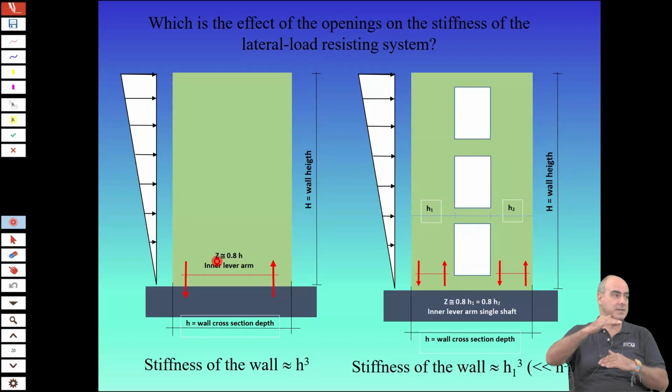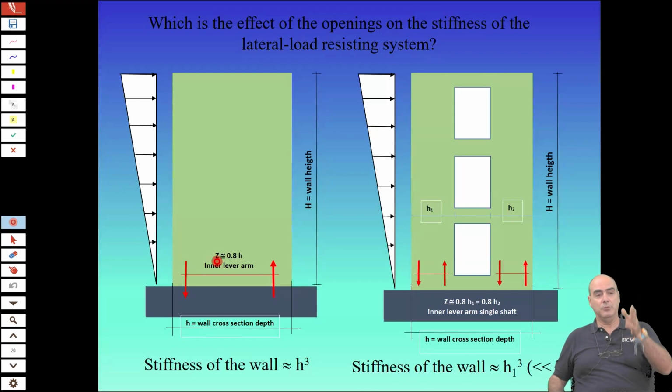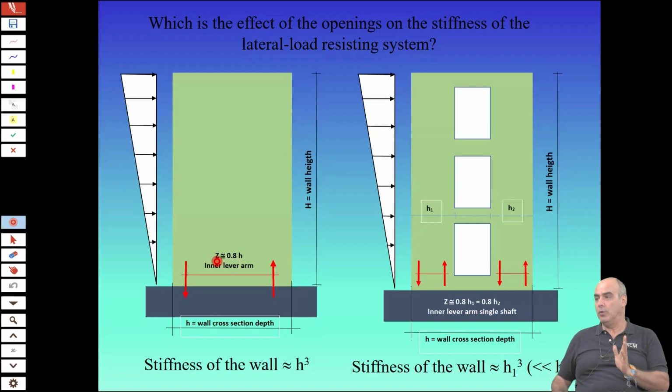Wind loading is constant up to a certain height, which, depending on the topography situation, can go from a few meters to about 10, 15 meters. But then up to about 200 meters height, it increases logarithmically according to most of the codes, but you can also linearize it, especially if you do not have very high-rise buildings, you can use a linear distribution. Well, first of all, the design of a shear wall is a matter of strength, but it's also a matter of stiffness. And the higher you go with the building, the more the design problem will become a matter of stiffness and not of strength.